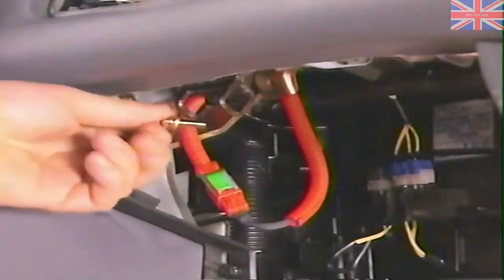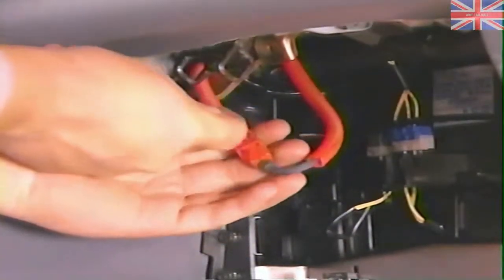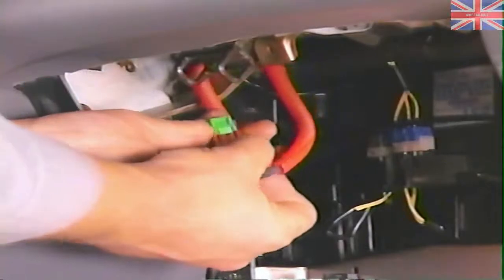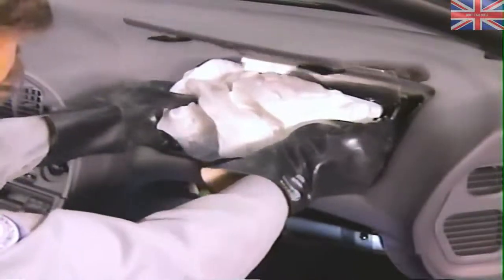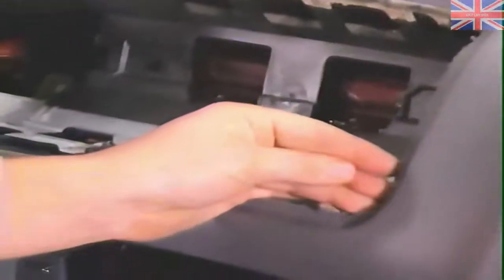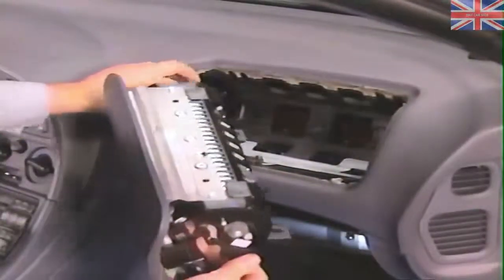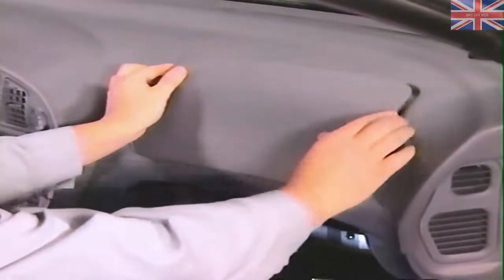Open the glove compartment and remove the 2 bolts and the 2 screws that fasten the airbag module to the instrument panel and disconnect the connector. The airbag can then be pushed up from the inside and lifted out of the opening in the instrument panel. Inspect the area around the instrument panel opening for cracks or damage that could require instrument panel replacement. Install the new passenger airbag by reversing the steps, being careful not to damage the instrument panel trim.